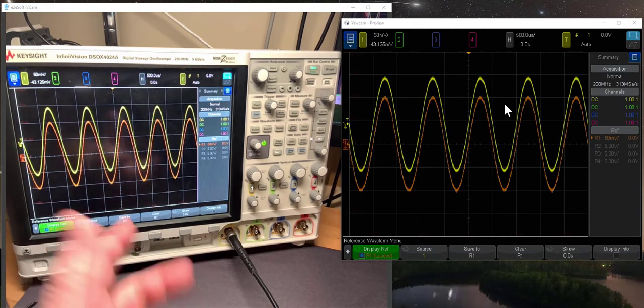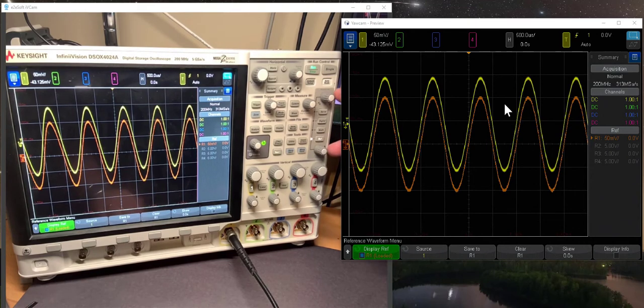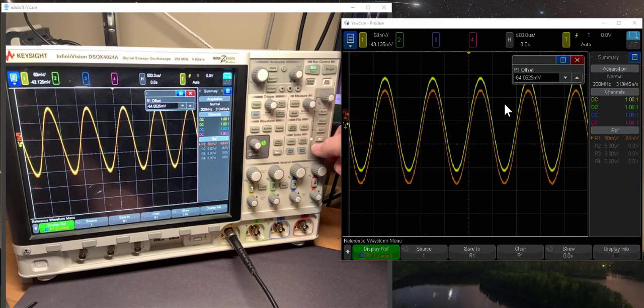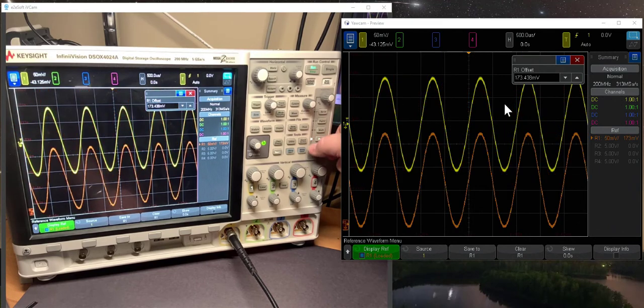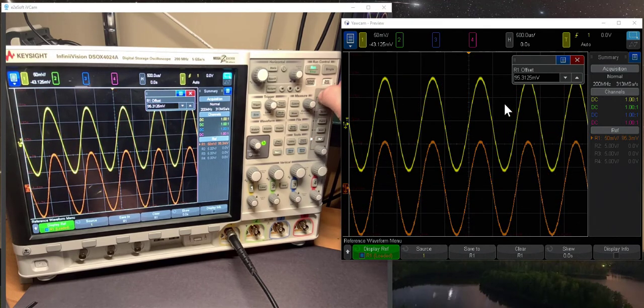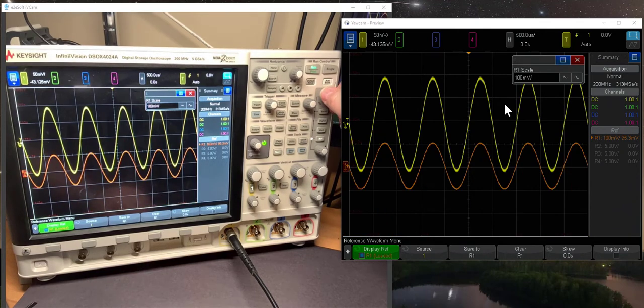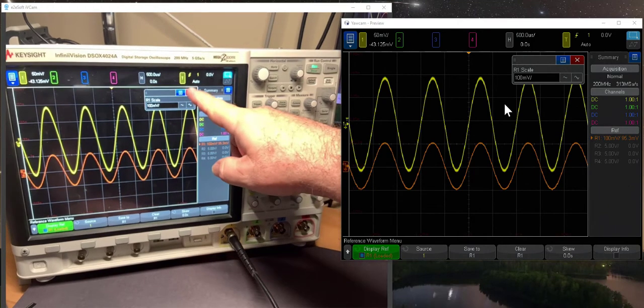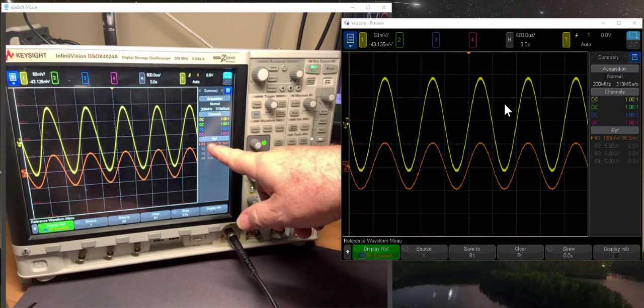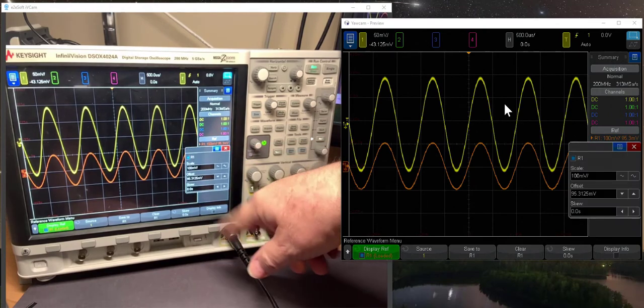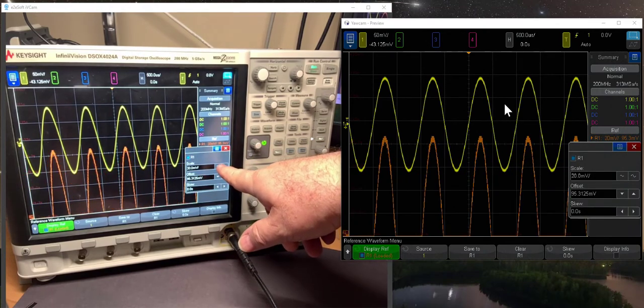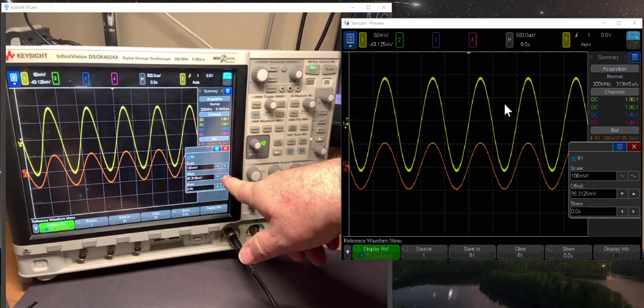In addition, I can change the scale, and the 2 knobs up here are to adjust the scale. So I can adjust the vertical offset position of the waveform. I can change the vertical height of that waveform as well. So I'm changing the scale with the 2 knobs. I can also, again, so many of the functions, we have 2 options. I can also come over here, push that in, and now I can manually change the vertical scale, and I can also change the offset.